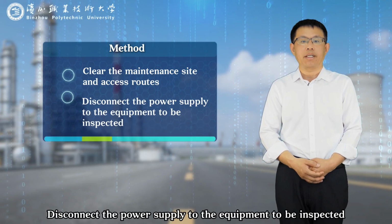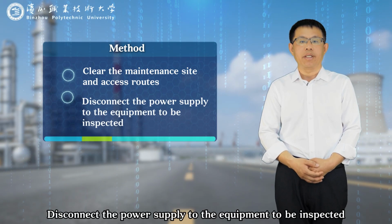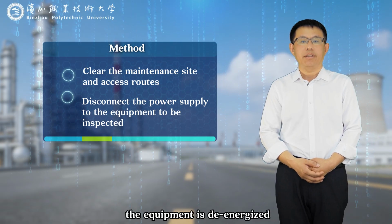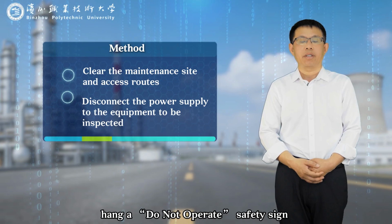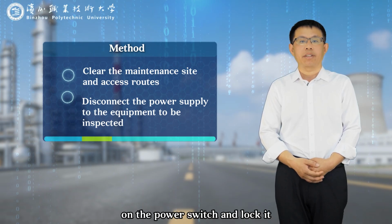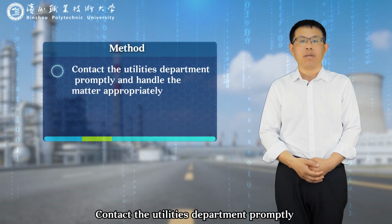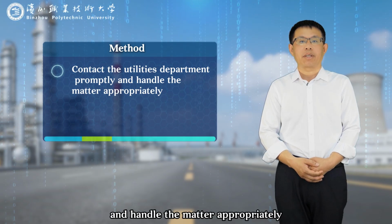Second, disconnect the power supply to the equipment to be inspected. After verifying through a test start that the equipment is de-energized, hang a do not operate safety sign on the power switch and lock it. Third, contact the utilities department promptly and handle the matter appropriately.